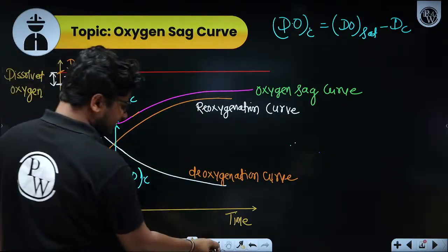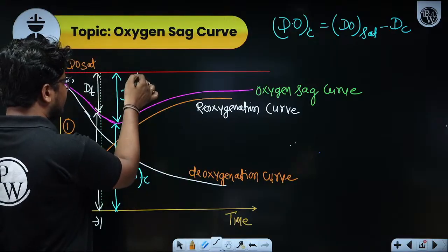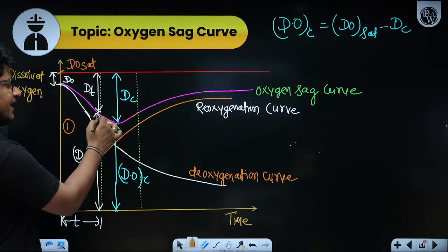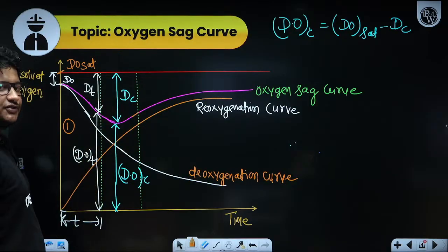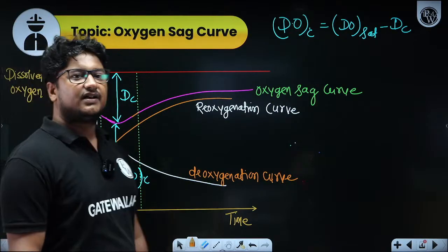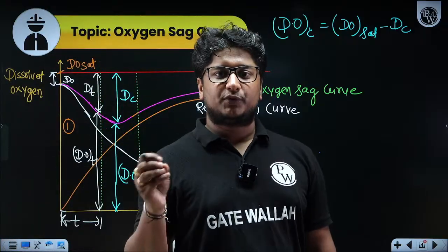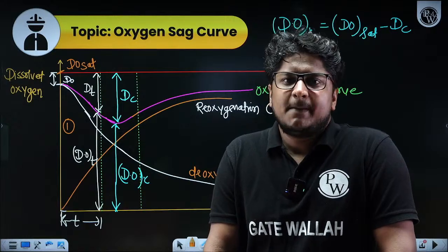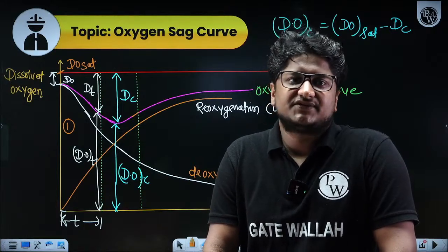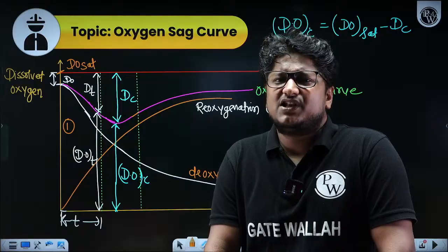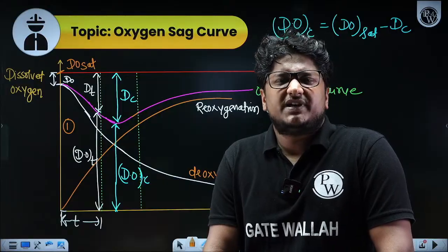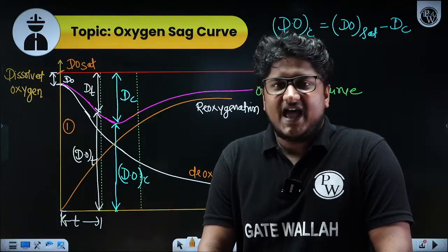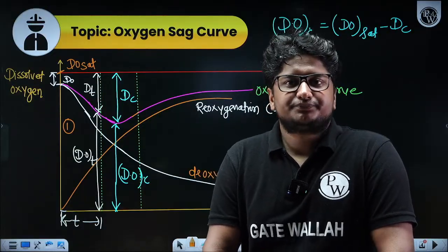Now, the second phase which we are talking about, the zone of active decomposition, lies here. Here you are getting the maximum oxygen deficit also. That's the reason I told you DO may go up to 0, because it is a very prime degradation phase. Maximum degradation is happening here. You will get a completely bad smell. The water becomes completely black for you.